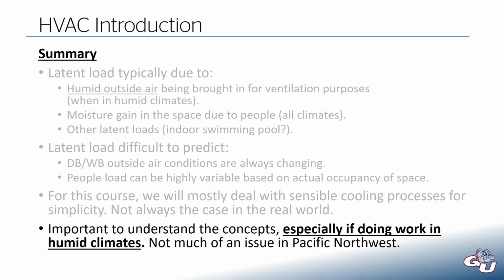To give you an extreme example, if you live in an extremely humid environment, you have to take your outside air coming in and hit it with a cooling coil just to remove the moisture from the air. And then after that cooling coil, you have to heat it up. So now you are cooling the air and then heating it up later, which is substantially, well, I was going to say wasteful, but it's necessary. It's what needs to be done, but it does use a ton of energy.